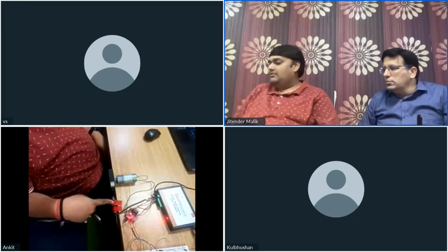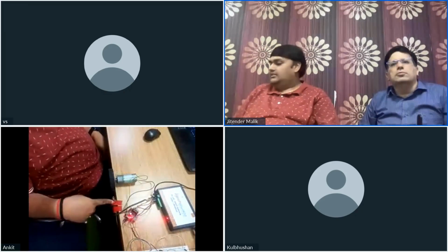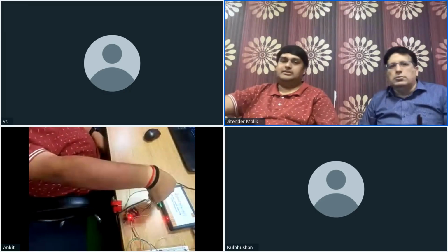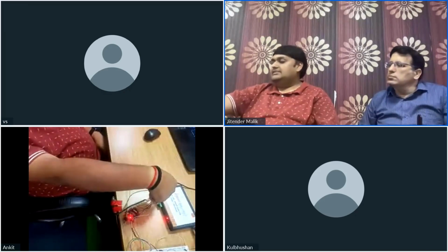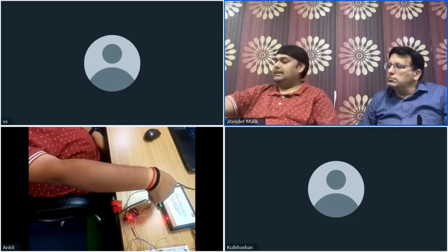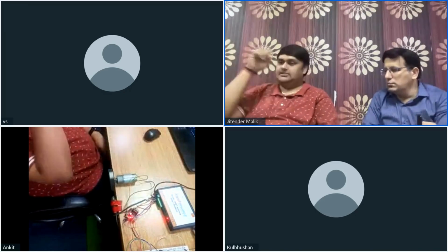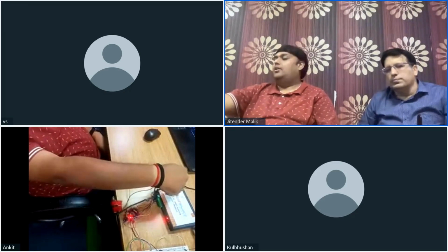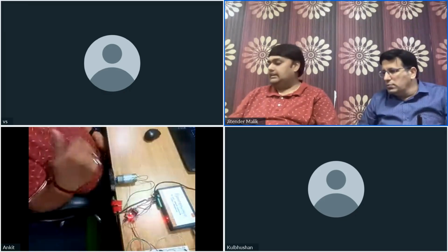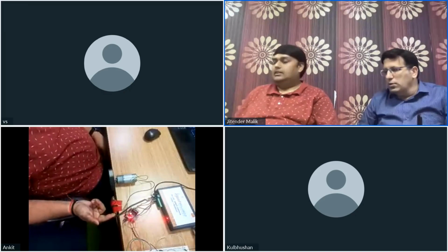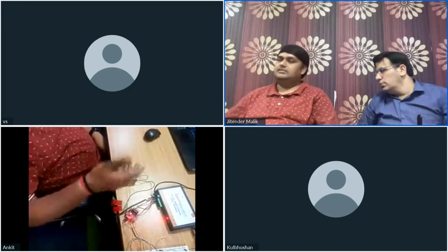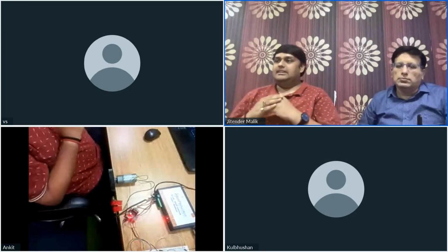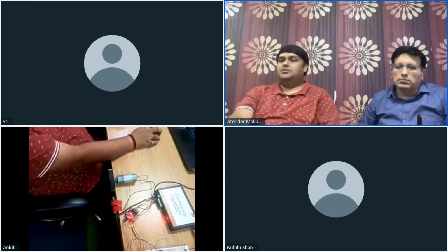And then we have a proximity switch that is connected to the digital read of the gateway that we have developed. This particular gateway is doing half the processing, and the rest of the processing is being done at the server. The exact RPM calculation is being done at this device. Also, this device is just counting the ticks received by this sensor, and then all this data is transferred to the cloud, stored in a database, and then we show the graph on the screen.